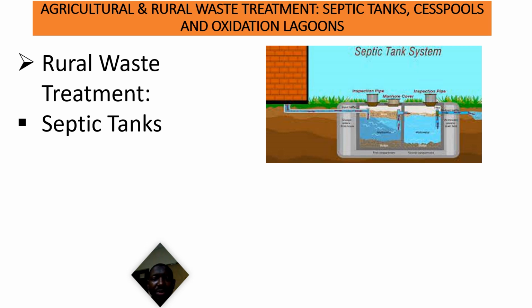This septic tank is essentially an equivalent of the primary sewage treatment, where the settling method will take place and so on. Now, sewage from the houses enters the sealed septic tank. The solid settles at the bottom. The liquid will now flow from the top of the tank into an underground leach field.